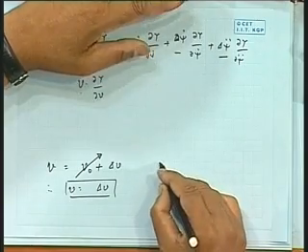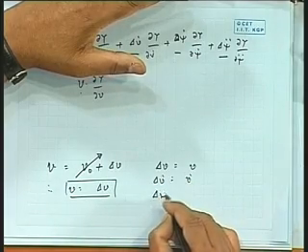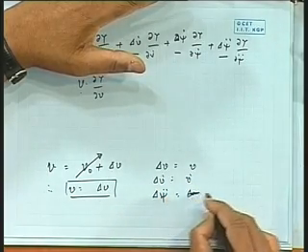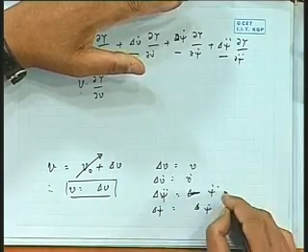Similarly, I can call delta v as v, delta v dot as v dot, delta psi dot as r, and delta psi double dot as r dot. So v and r, v dot and r dot have set up my forces. Now this force equals mass times motion. This equation of motion will tell me the solution for the velocities that were generated because of some disturbance, which in turn generates a force.